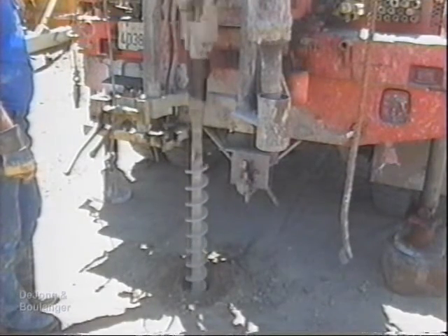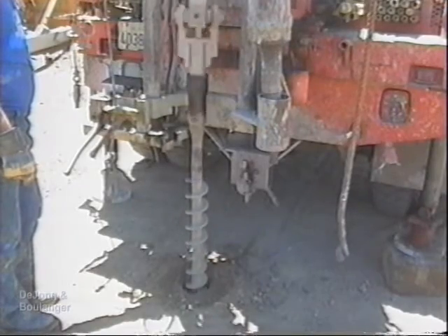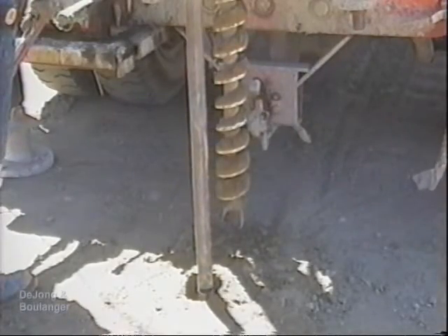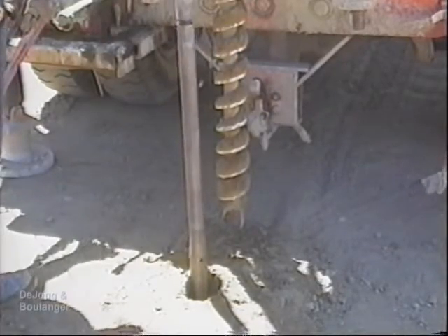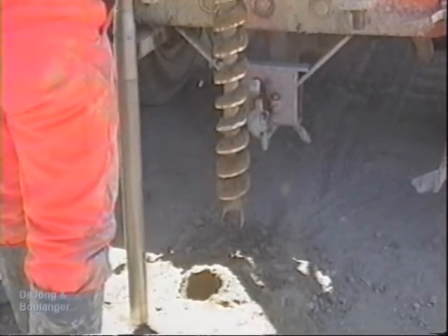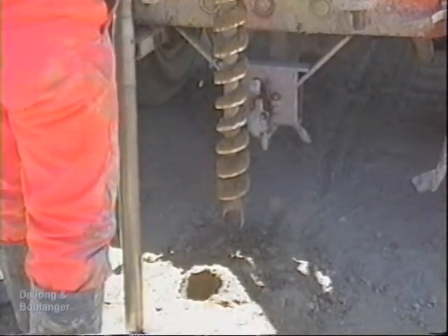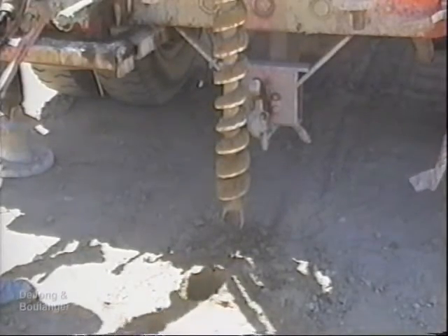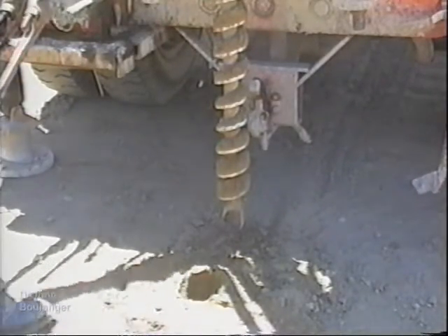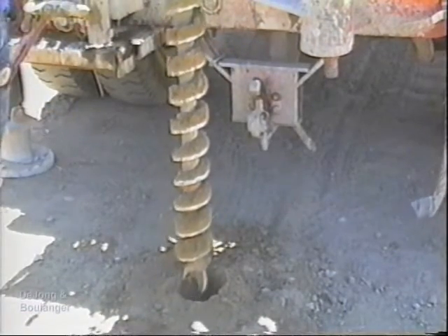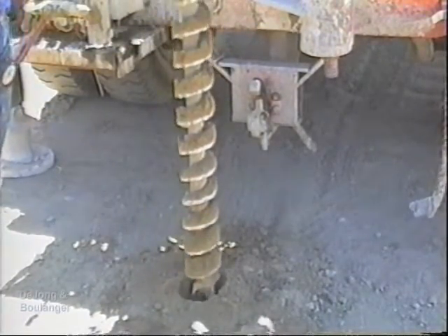Upon reaching a specified sampling depth, the borehole is cleared of cuttings. The augers and bit are removed by a cable. A sampling tool is then lowered down the open hole to take a sample from below the hole bottom. After sampling is completed, the bit and flights of auger are lowered back down the hole, reconnected to the drill head, and drilling is resumed. This drilling approach only works for soils where the open borehole does not collapse.